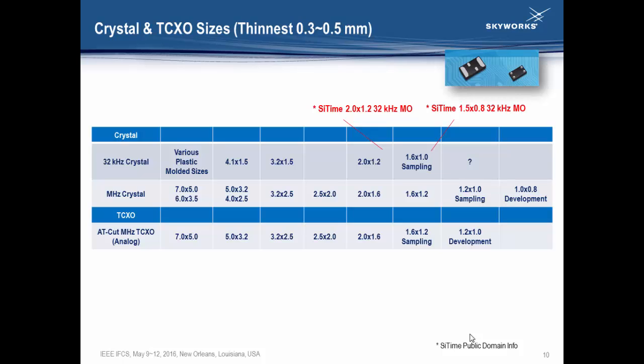Of course, for a MEMS oscillator, there's one problem: you have to drive it. You can see the MEMS oscillator here has two extra pads because you need to drive it. It's an oscillator. For the crystal, it's just a passive device.